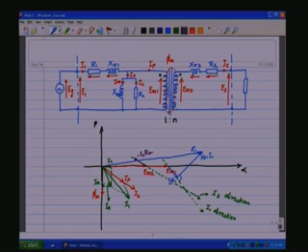And from this direction taking 90 degrees anti-clockwise would be the plus j sigma2 direction of the voltage drop. We are now subtracting that and therefore, we have x sigma2 I2.